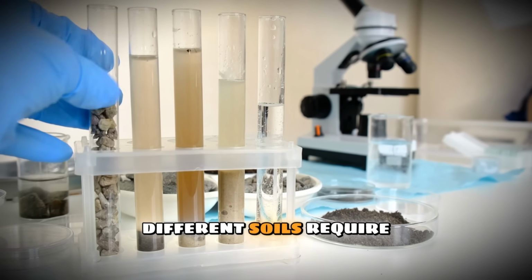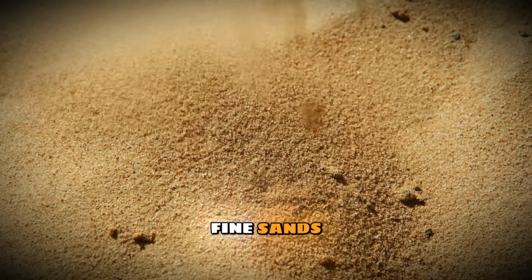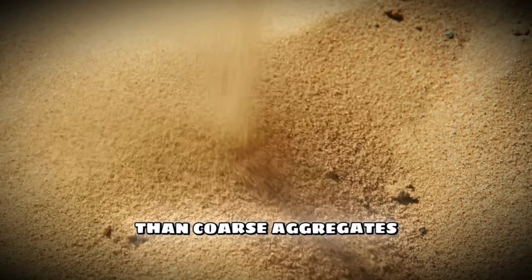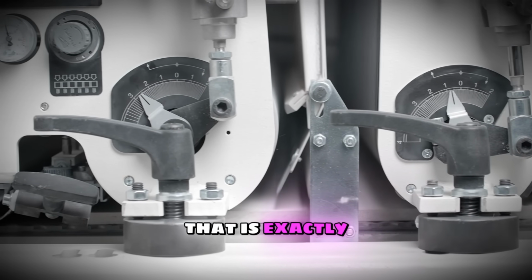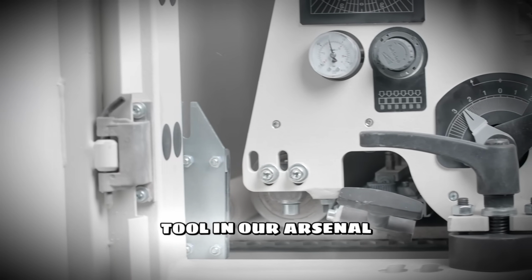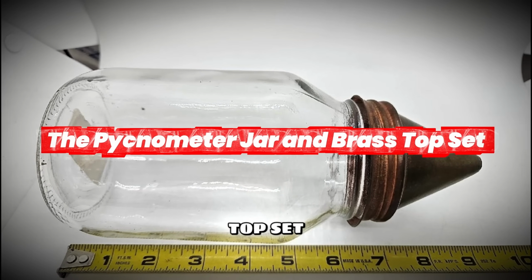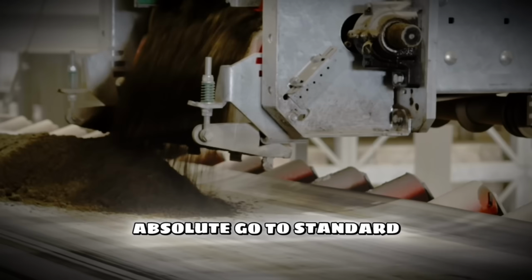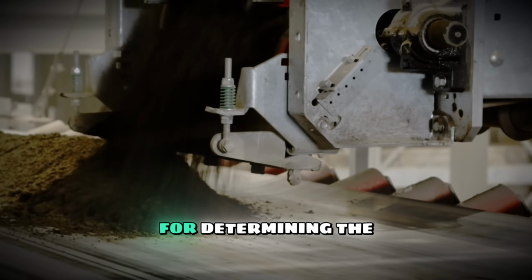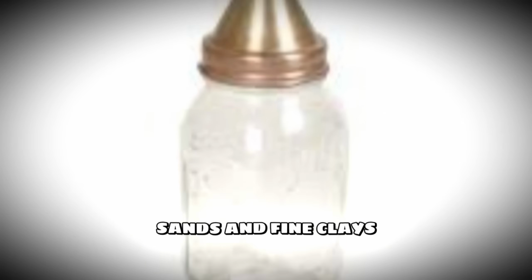Different soils require different testing methods based on the size of their particles. Fine sands require different tools than coarse aggregates. That is exactly why we have specialized equipment. Let's break down the first essential tool in our arsenal. First up, we have the picnometer jar and brass top set. This is the absolute go-to standard for determining the specific gravity of fine-grained soils, like sands and fine clays.